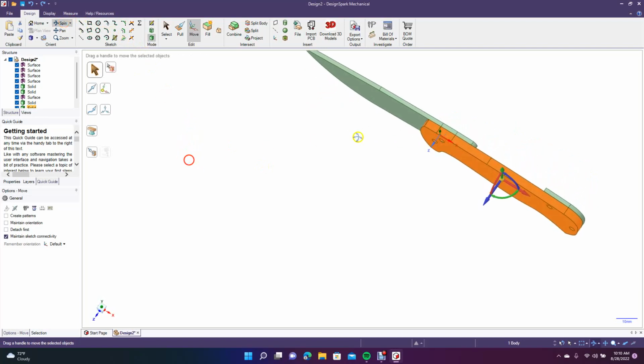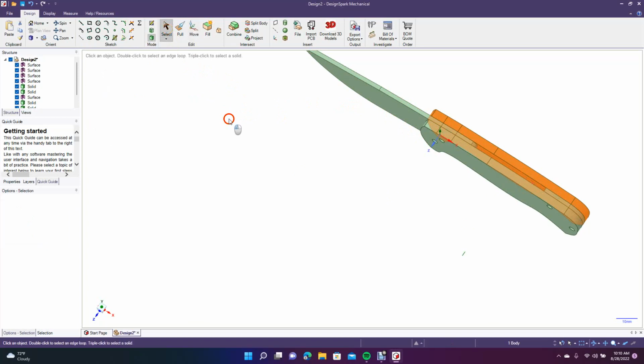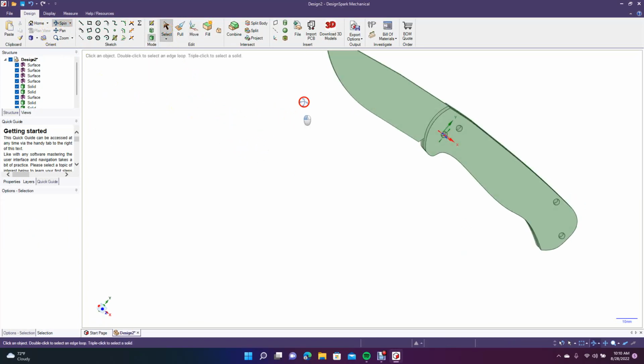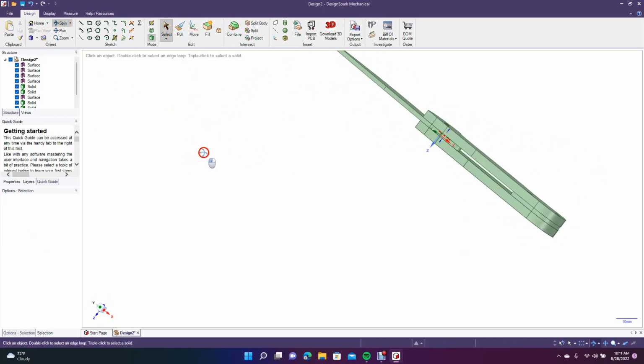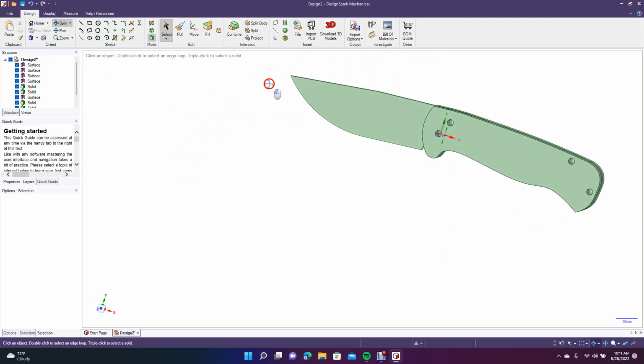All right, so the scale is 3 and the blade is 2, so I have to move this over 5. So let's do a copy, paste. Let's go to move. Let's grab that blue and move this over. Type in 5 millimeters. Oh no, actually 6. Okay, this scale is actually 4. I was thinking it was 3 for some reason. So we'll go ahead and click off. Now we'll spin this. Okay, this is going to be our drop.